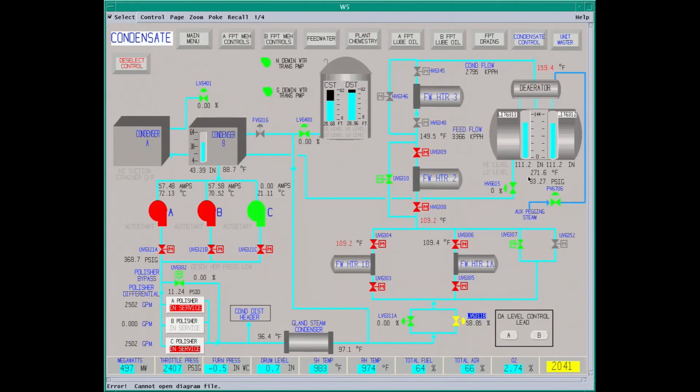Okay, here's the deaerator in the plant. Deaerator's storage tank's right here. Here's the deaerator. Big thing to worry about is your level. 67 inches you trip one feed pump, and 64 inches you trip the other feed pump. So you come offline. You have a drain valve that goes back to the surface condenser.